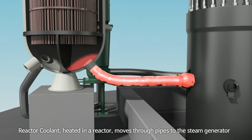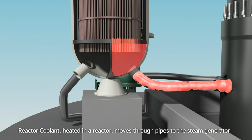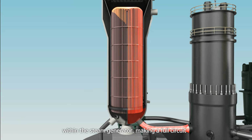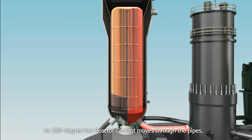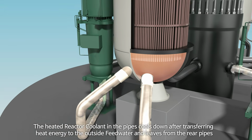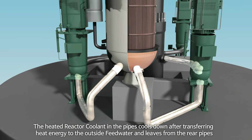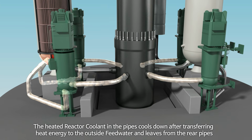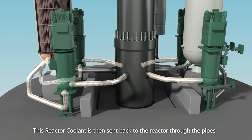Reactor coolant, heated in a reactor, moves through the pipes to the steam generator. Hot reactor coolant flows through approximately 13,000 U-shaped tubes within the steam generator, making a full circuit. As 320-degree hot reactor coolant moves through the pipes, it heats feed water outside the pipes. The heated reactor coolant in the pipes cools down after transferring the heat energy to the outside feed water and leaves from the rear pipes. The reactor coolant is then sent back to the reactor through the pipes.